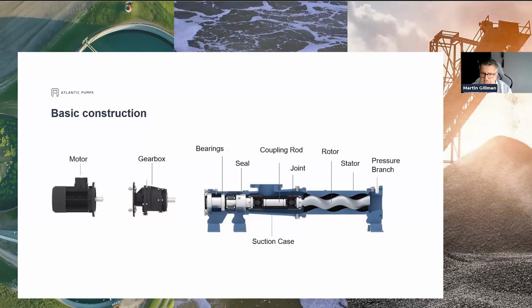But the gearbox also helps us with a little bit of physics as well. It gives us a little bit of extra torque, providing it is selected correctly. And we need that extra torque boost for starting and running this kind of pump, because it relies on an interference fit between the front end there, the rotor and the stator, in order to perform its function. That interference fit, of course, requires a drive that gives extra load. So I talk about dumbing things down. We're not spinning a fan here. We're turning a rotating element within a pump with lots of friction, lots of resistance, including the resistance from the pumping system itself. So we need a little bit of extra, I call them beans, to get the thing going and keep the thing running.